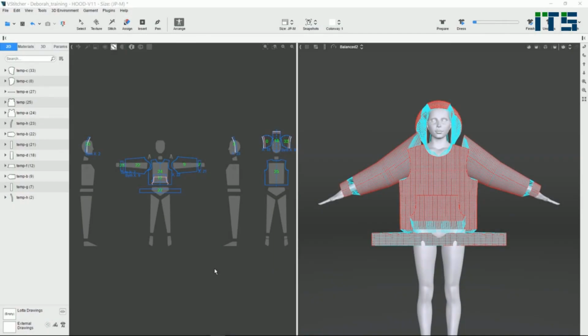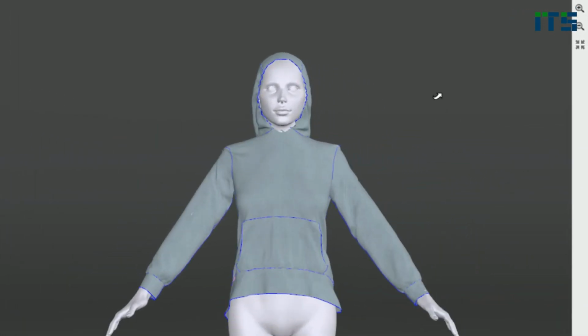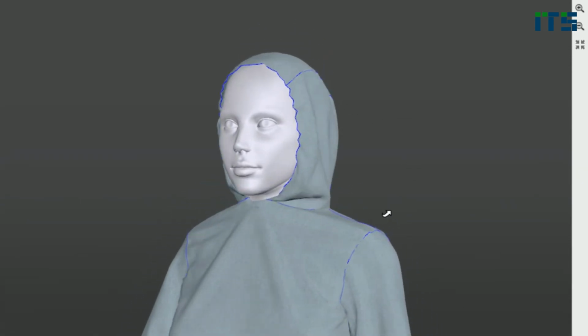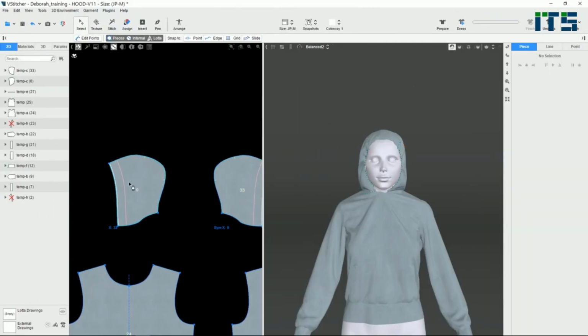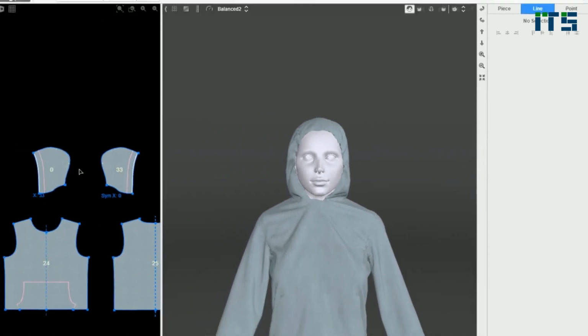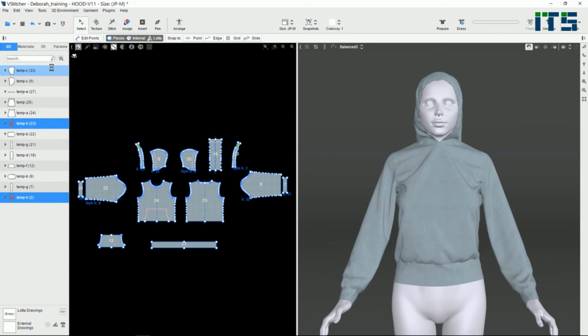In order to demonstrate layer dressing, let's disable the hoodbands before our first simulation. We select the patterns and choose the command "Don't use selected." Then we simulate. Notice how the hood looks bunched up because of the shrinkage we added. We then enable the hoodbands by selecting them and choosing the command "Use selected." Then we resimulate to sew the hoodbands over the hood.